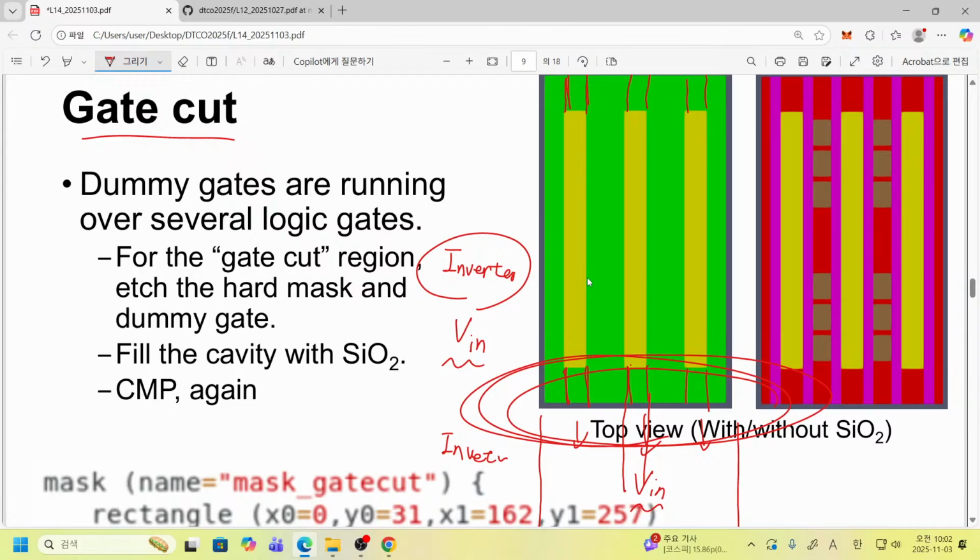At the beginning of our FinFET technology, the gate cut was performed even earlier. But in the case of this FinFET, the standard position to perform this gate cut is after silicide. And if we dig out another research paper, we can find some attempts to even delay the gate cut until after, for example, RMG.